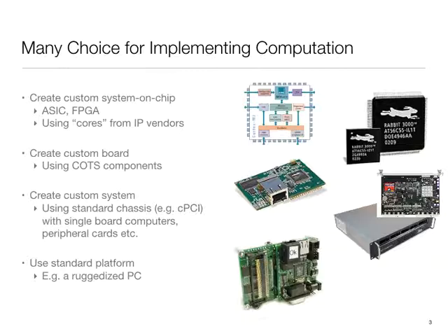ASIC basically says every transistor belongs to you. FPGAs are chips which have a whole bunch of transistors and wires, and you can program the connectivity between the transistors or the gates. They stand for field programmable gate arrays. They are arrays of gates which are programmable in the field.